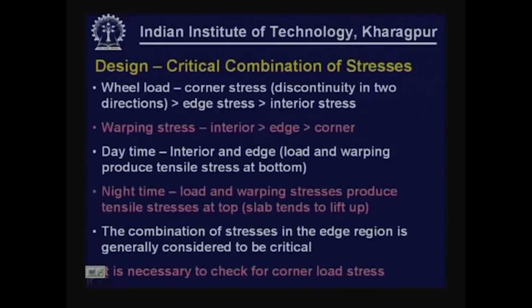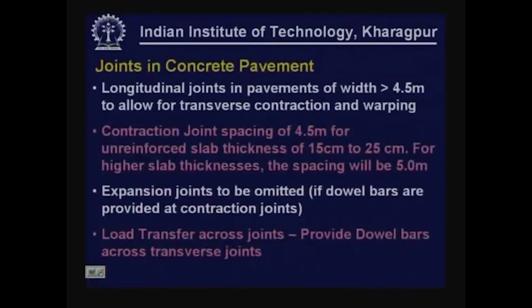The combination of stresses in the edge region is generally considered to be critical. So, it is necessary to also check for corner loads. Although we are concerned about the edge region, IRC recommends that we should also check for the corner load stresses.